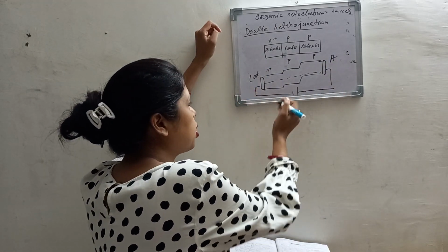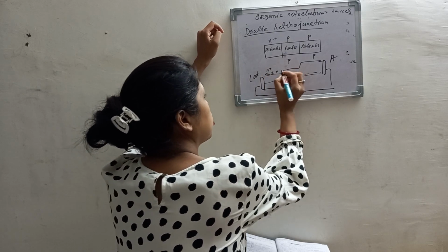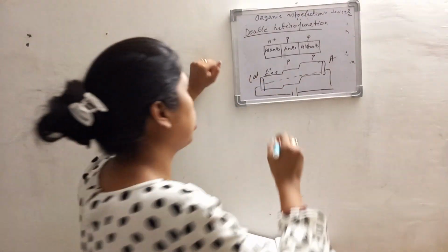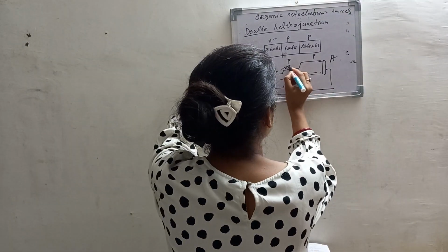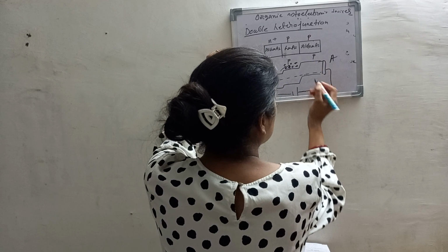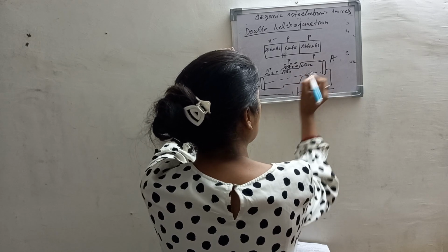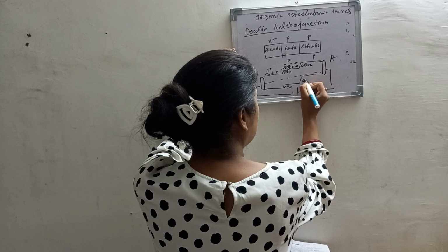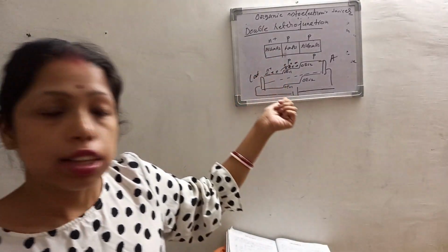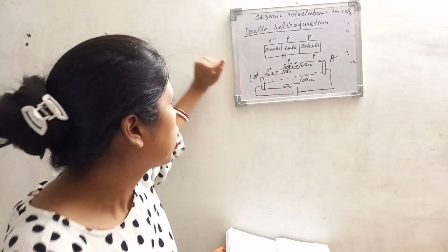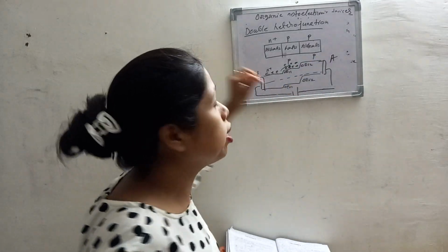Okay. Now here if we apply the negative voltage, in the same way, the electrons, okay, will be repelled away from the cathode terminal and move towards the P-type gallium arsenide. Okay, here all the electrons are accumulated. Here you can say this is the delta EC1, and you can define delta EC2, delta EV1 and delta EV2. So this energetic gap, delta EC1, is less as compared to delta EC2. So electrons can be repelled away from the cathode terminal and transport easily towards the P-type gallium arsenide.